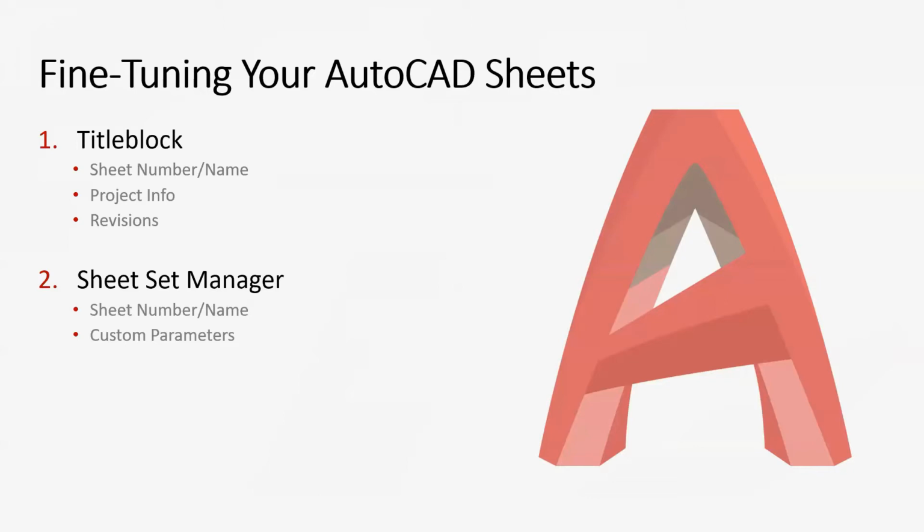Again, it'll be dictating that sheet number and name that we have adjusted in our title block, but we can also create custom parameters. And then named views. Named views are really good because we can use them both in model space and paper space. So they can quickly be translated into our viewports in our paper space, but we can actually also use them in the sheet set manager for another powerful tool.